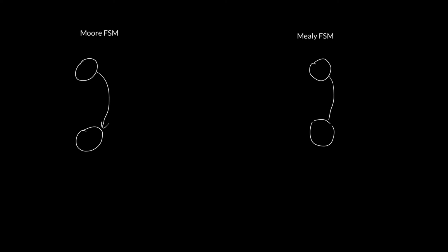There are two types of finite state machines. A Moore Finite State Machine has the property that the output only depends on the current state, and that will be explained presently. The more general finite state machine is the Mealy Finite State Machine, which does not have that limitation. In both cases, a state diagram involves nodes, which are denoted by circles, and transitions between different nodes, denoted by arcs, like this.